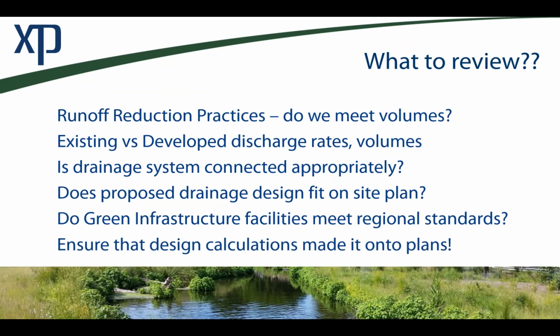And really the last one, I touched on it already once, but it is, in my opinion, the easiest thing to have be the mess up that could occur: just simply not having the design calculations actually make it into the plans. Not actually having the pond be the volume storage that you are designing towards, then what actually gets put into the design plan, which will get built, right? So that construction document set doesn't really match what your assumptions were. So those are all the items that I'd say that we need to review.